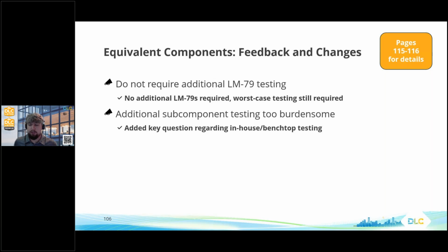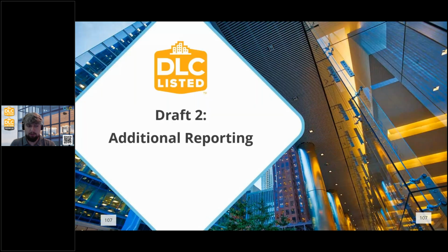There's no additional LM79 tests required for demonstrating compliance, but the worst case for all subcomponent variations still needs to be tested. Additionally, just like I mentioned in driver lifetime details earlier, we're looking for input on whether or not we should accept in-house or benchtop thermal testing to demonstrate compliance at the subcomponent level. And with that, I'll conclude this section and we can go ahead and move to the last section focused on the additional reporting requirements in Draft 2.